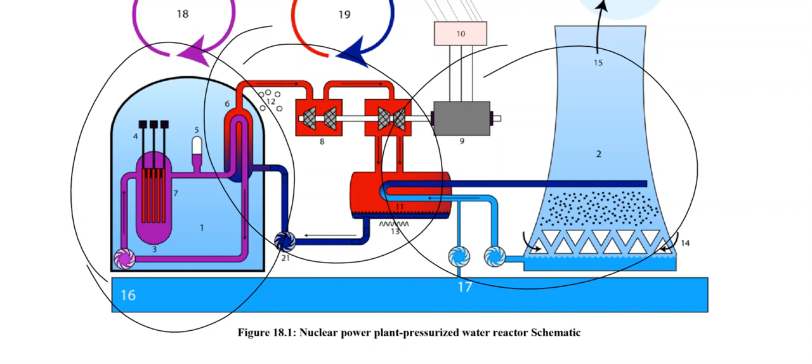It is actually a boiling water reactor, BWR. So it is having a huge amount of heat, and this heat is recirculated. It is attached to a heat exchanger, or what we call a steam generator. In this process, steam is generated in the steam generator, and superheated steam is formed. This steam is directed to a steam turbine, a high pressure turbine, and then a low pressure turbine. Once it has circulated in the turbine, it is condensed, pumped back to the steam generator, and so on and so forth.